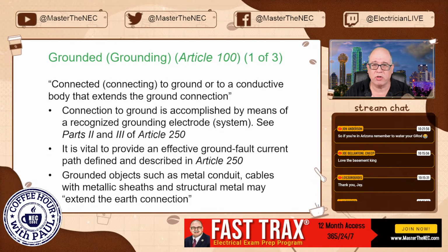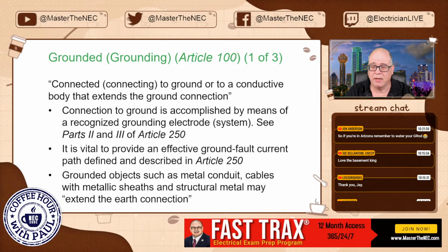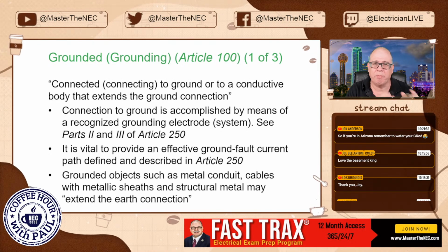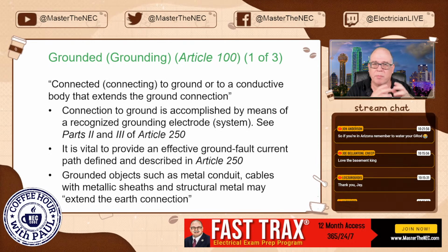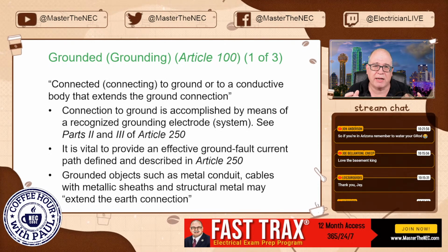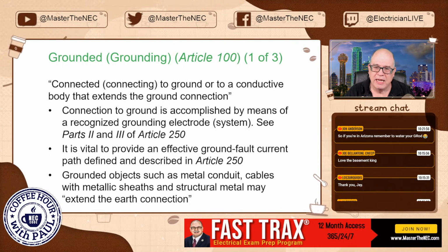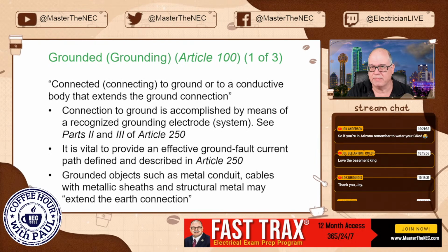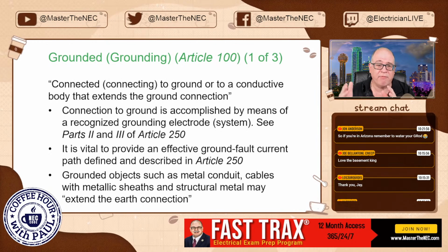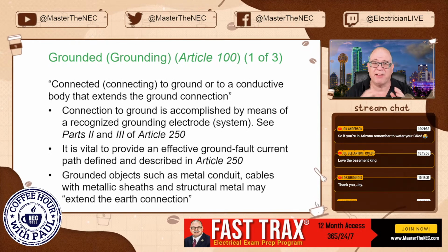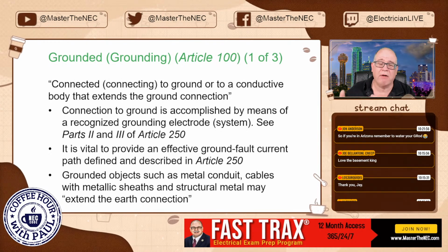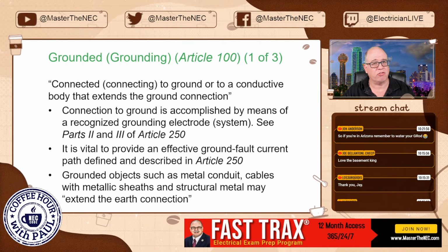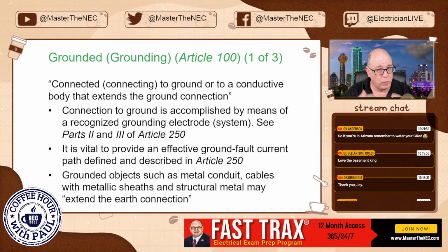You know what you're doing. You go through the schooling. It's all an intended thing. When we use couplings and we use the set screws or compression, when we terminate equipment grounding conductors, we do all this, it's intentional. We have to have some thought into it, okay? Now, paths that ground fault current takes that aren't the effective intended path are still ground fault current paths, okay? But they're not ones that we construct. We want it to follow the paths that we construct.